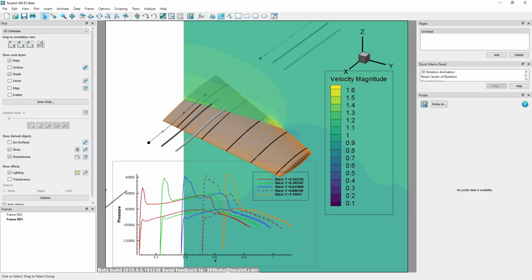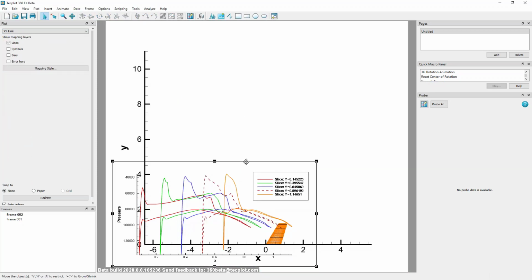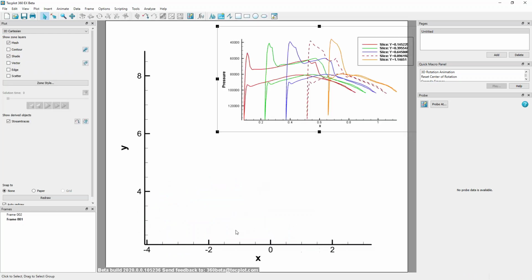A map view of a terrain where Z changes with X and Y: can I tell Tecplot to show in an XY view only the topmost layer of nodes? Because sometimes it shows contours from underlying layers. This is an interesting question. In geosciences, we can open FEM data, and if you're showing a 2D plot, if Jared were to go to the plot sidebar and select the 2D Cartesian menu, if you're in 2D, Tecplot has no concept of depth in that view.